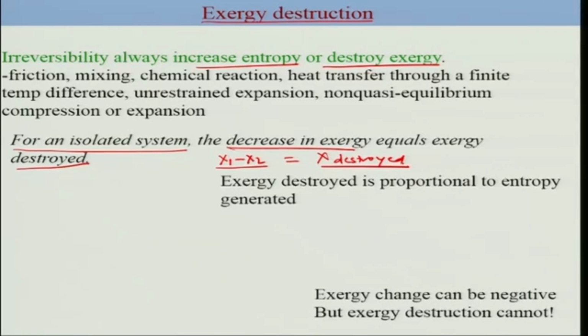Okay, we are saying that exergy destroyed is nothing but X destroyed is equal to T0 multiplied by S generation. So it's very clear that your amount of exergy which is destroyed is directly related to your entropy being generated. Exergy destroyed is proportional to the entropy generated.